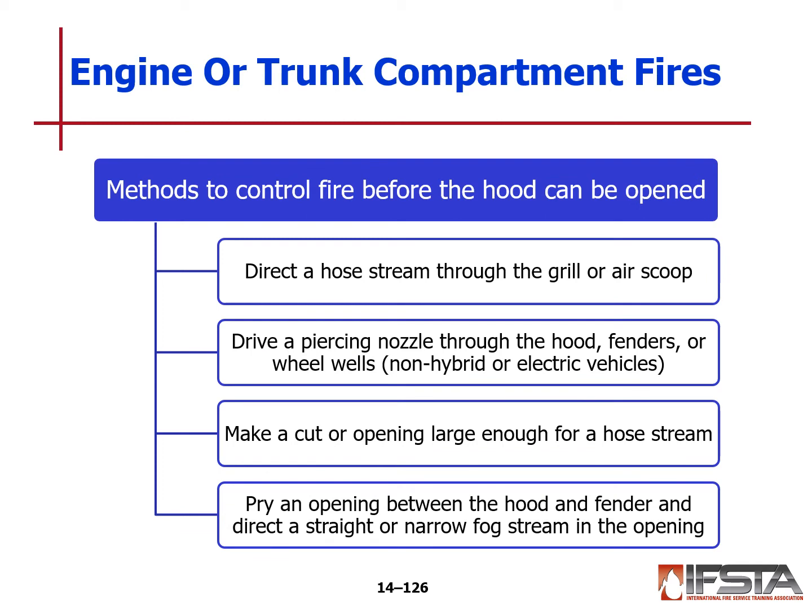Controlling fires after the hood has been opened, direct the hose stream around the grill, around your hood scoop, in and around the engine compartment. If you drive a piercing nozzle through the hood, the fenders, and the wheel wells, be cognizant of hybrid and electric vehicles. We want to make a cut or an opening large enough for the hose stream so we can apply water, and pry an opening between the hood and fender and direct a straight or narrow stream within that opening as well.